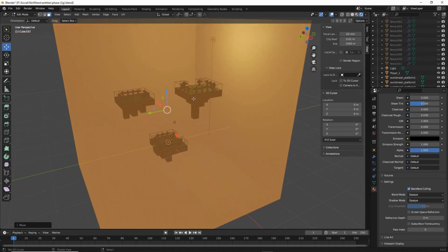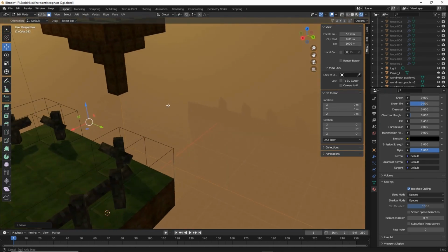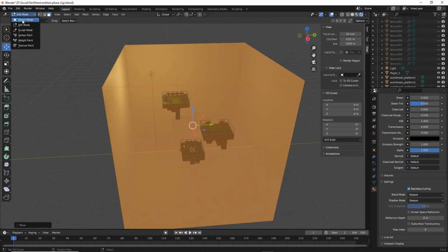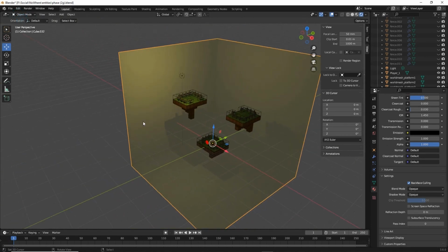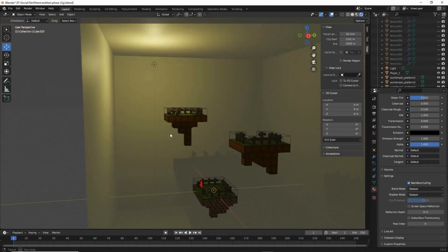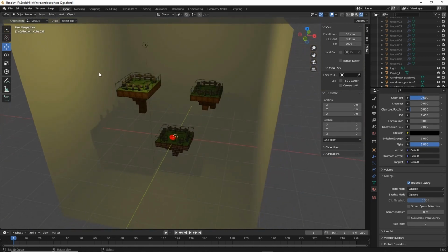So what we'll need to do to this is assign a background node-based material so that we don't get any shadows appearing on the sky, because obviously you wouldn't get that normally. Exit edit mode into object mode, and that is our sky. And that just contains everything.